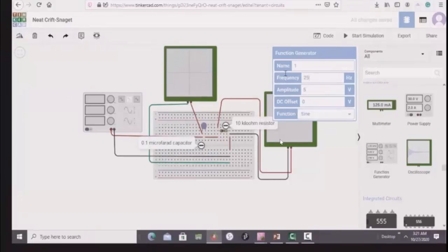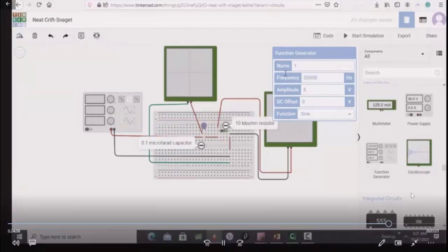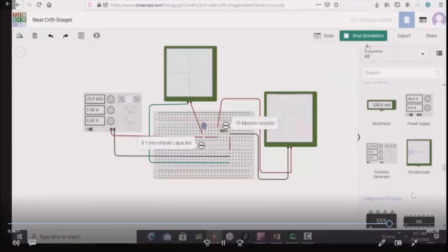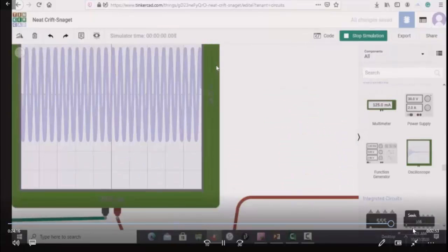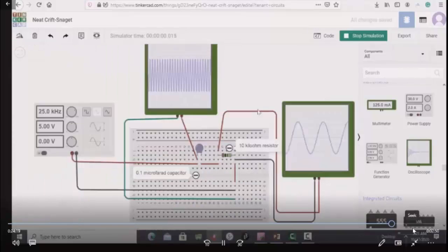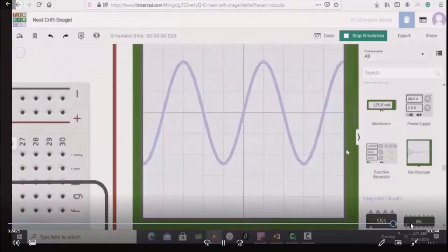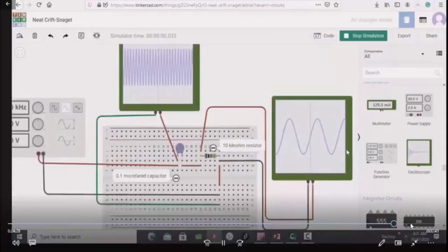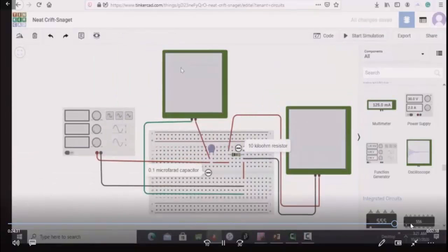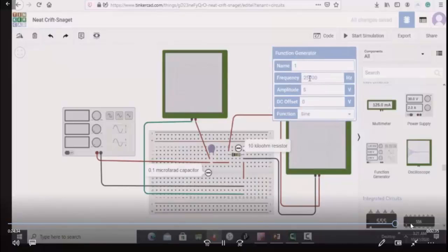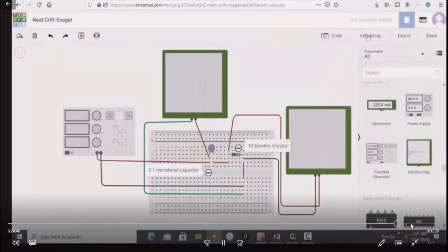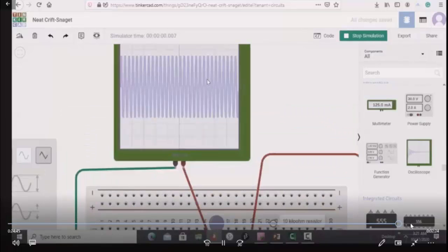And then I go on increasing the frequency again, and then noting down. So this is for 25,000 hertz. I start the simulation, and I note down the peak to peak value, and I'll go on like this till I reach a value of 30,000. Since my cutoff frequency is what? My cutoff frequency is 3,000. I started this experiment with 3,000. When I took the 5 nanofarad capacitor, I adjusted my cutoff frequency to be 3,000 hertz, 3 kilohertz. Is that clear?